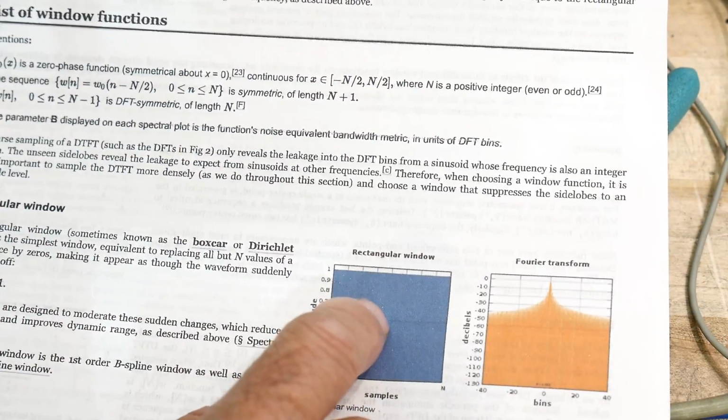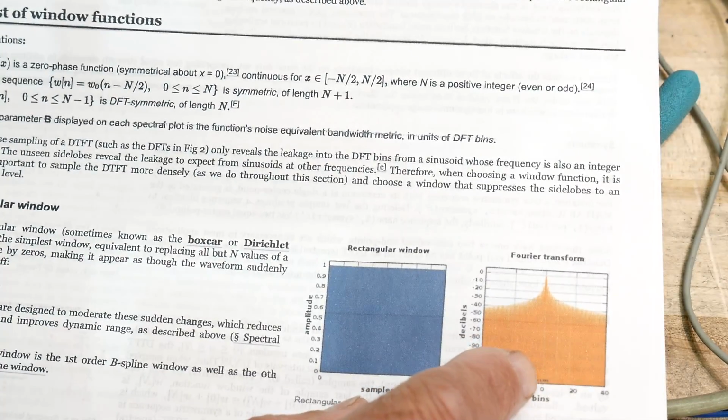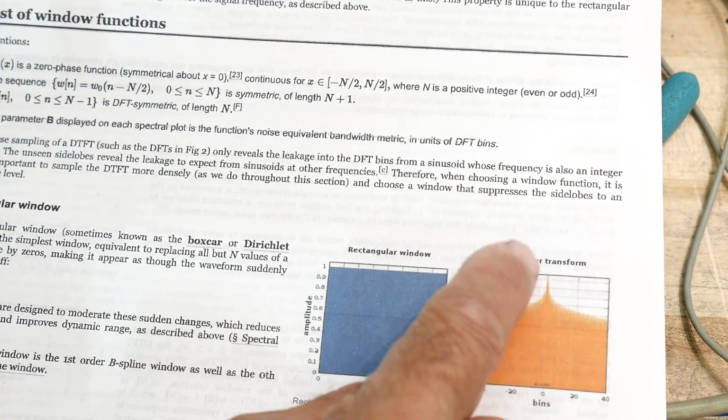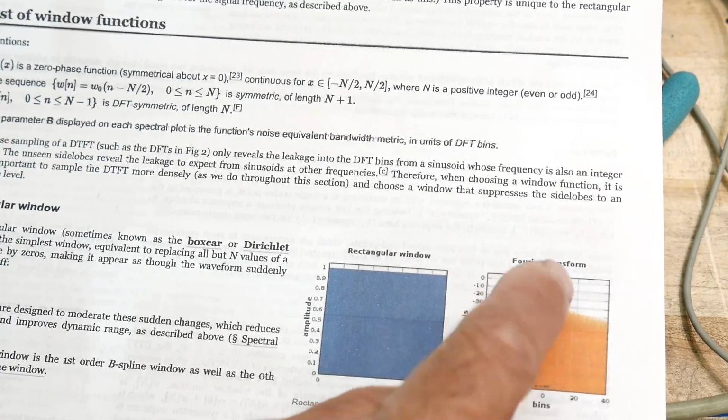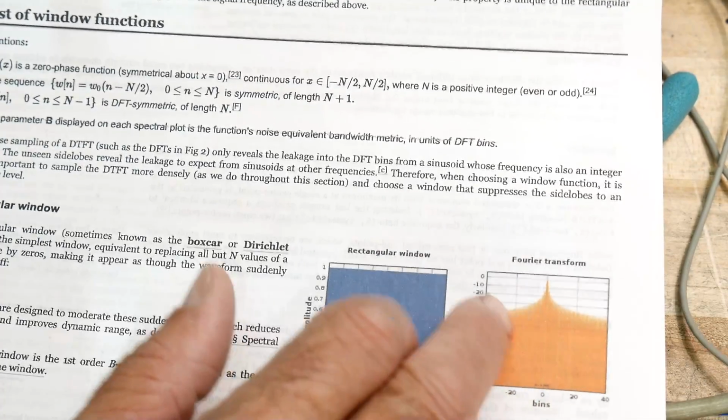And if you do a Fourier transform of this box, you'll end up with that, which looks a lot like that first picture I showed you on the FFT. You had these big skirts, you had this big roll off over here, and that's why, because it defaults to rectangular windowing. Okay, so this boxcar averaging.